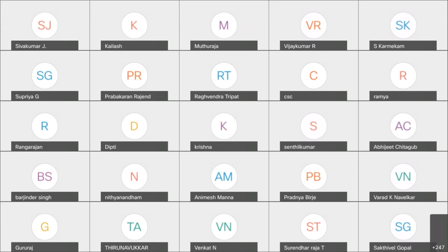If I'm using some microcontroller from a customer, and I'm taking that controller into my project, do I need to consider their FIT as it is, or do I need to consider it according to my application? See, for example, the failure rate aspect. For a passive component like a resistor or capacitor, we need to understand whether it is a base failure rate or based on the way the component is being used in the circuit. If the failure rate is calculated according to how it is being used in the circuit, then you can use that directly.